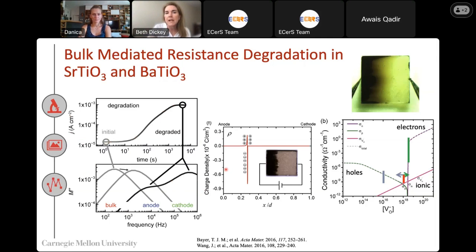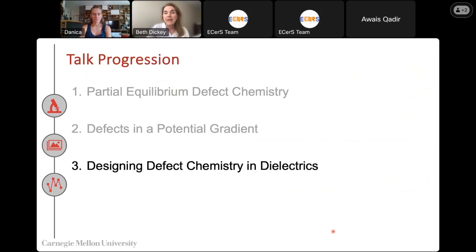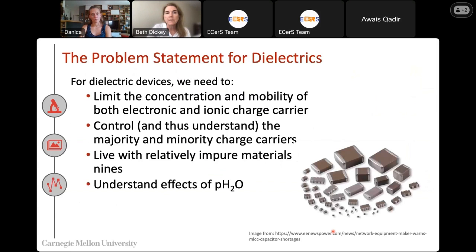I won't go into that, but the picture is, you know, qualitatively the same as back when Vosser originally did these works, is that you form an internal p-n junction in the material, okay? And then you'll have very high conductivity in one state, in one polarity, and low conductivity macroscopic in the other polarity. And I'll finalize by talking about just what's going on in the dielectrics community, in particular with respect to